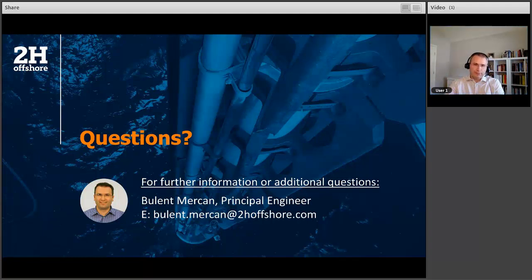Next question is, riser VIM fatigue can be critical for spars. Did you determine riser fatigue due to VIM using field measurements? Yes, for spars, the vessel induced motions, VIMs, are important, and that is also affecting fatigue in the riser at low frequency. For this specific monitoring campaign, we did not track the riser motions due to VIM.